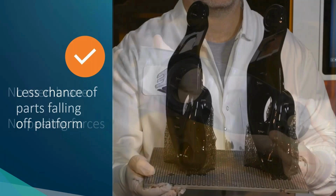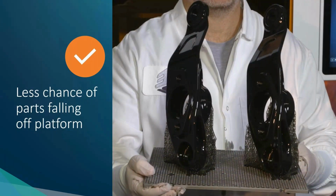And another point, when you do print these larger parts, for example, if you're printing them the right way up and they're supported on a base inside the resin, as you can see here, these PSLA parts are built nicely upright. There's no chance of these parts falling and damaging hardware such as the membrane or even the projectors. Remember, the DLP systems have those projectors underneath the part. So there is a chance those heavier parts can fall off of their supports, do quite a lot of damage to expensive hardware underneath, whether it's projectors and at least membranes as well.